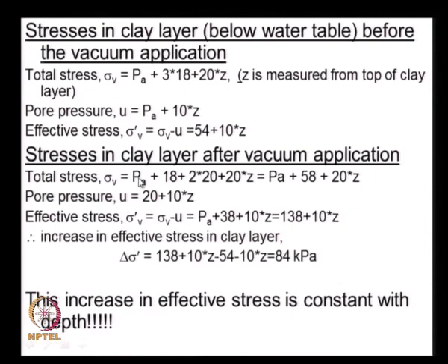The stresses in the clay layer after vacuum application: the total stress is PA plus 18 plus 2 times 20, because 18 is for the top 1 meter of sand, which is unsaturated or without water, and 2 times 20 is the unit weight of 2 meters of sand, plus 20 times Z, the unit weight of clay soil times Z. That is PA plus 58 plus 20 Z.